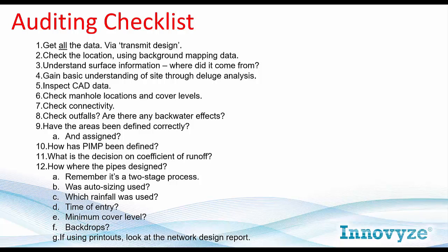Remember that FEH is now the most recent data, so has that been used, and is it appropriate to be used? Time of entry, fairly standard. That's how long the water takes between landing on the ground and making it to the manhole. There's a table in the Wallingford procedure which describes that. So is it in accordance with that sort of definitive advice about time of entry?